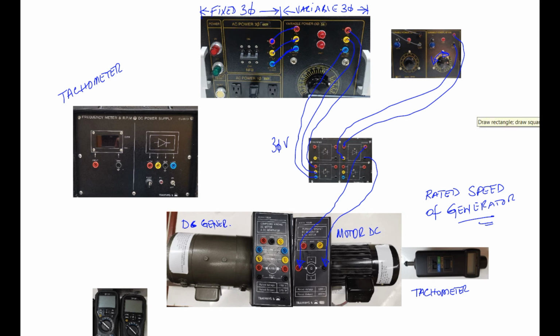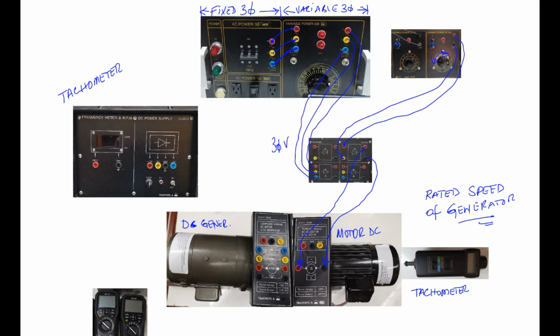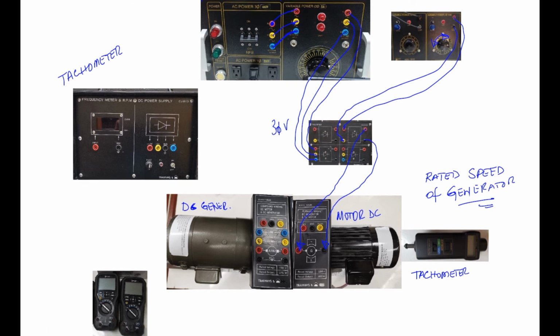let's change the color here just to make it more clear for us. We'll change the color here to red. Now here we're going to excite through an ammeter. So we need our ammeter to be in the path. We take our plus, going to our, let's say for example, this is our ammeter. We can connect it in milliamp or amp, depending. So let's start with milliamp. If the current is a little bit bigger, we can change it back to the amp connection.